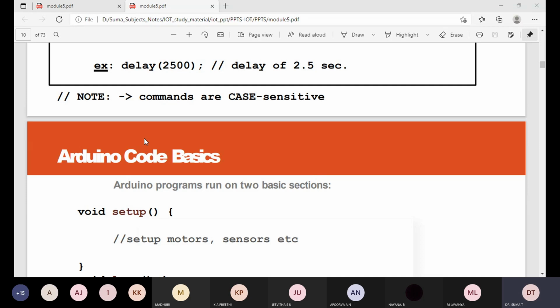Then there are the digital input and output pins and their usage: the pinMode method, digitalRead(pin), and digitalWrite(pin, value). The syntax for digitalWrite is pin comma value. digitalRead(pin) reads a value from a specified pin, with the result being HIGH or LOW. For example, val = digitalRead(inputPin). digitalWrite(pin, value) outputs HIGH or LOW on a specified pin. digitalWrite(pin, HIGH): the pin is set to HIGH.